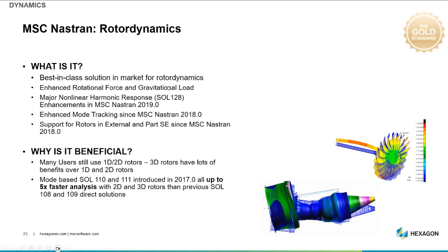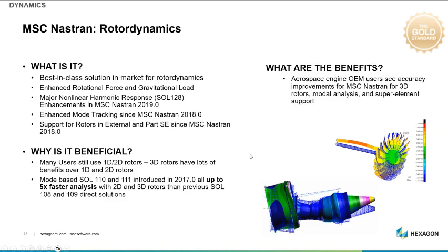So the rotordynamic capability allows us to solve these kinds of structures, but also to couple that with the rest of the structure to see how it interacts with the structure. So not everything has to spin, only certain parts. This can be done using anything from the simplest case, beam elements, to special axisymmetric elements, all the way up to full three-dimensional models, solids, shells, and so on.